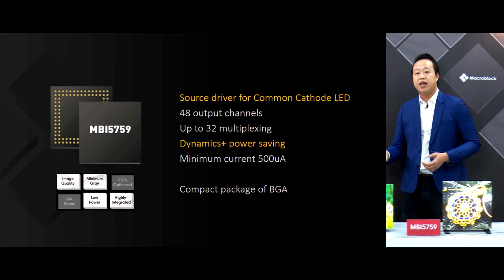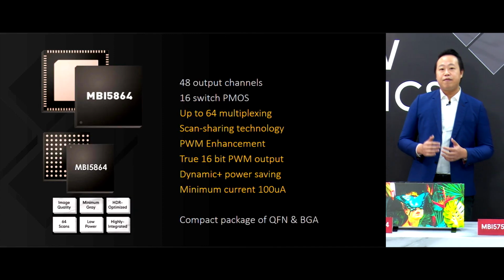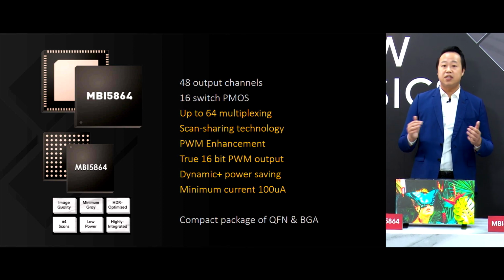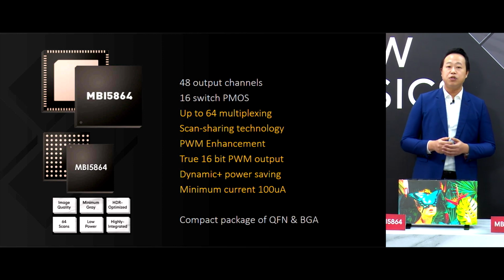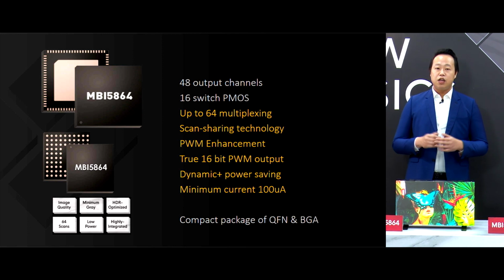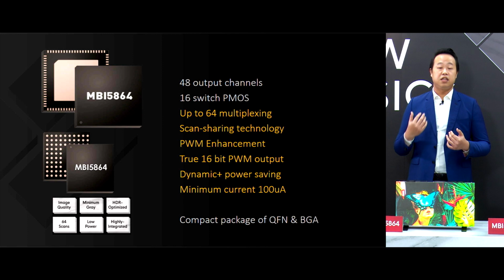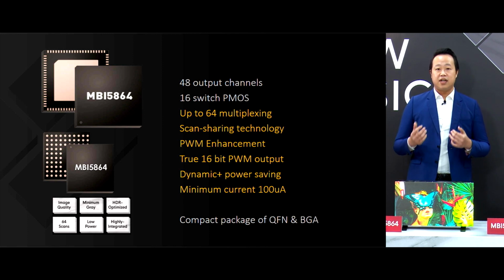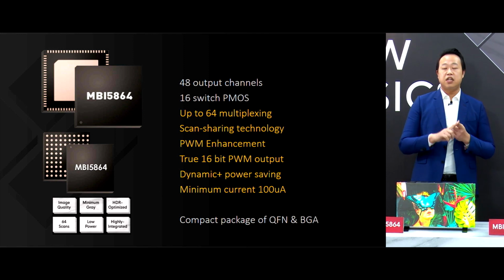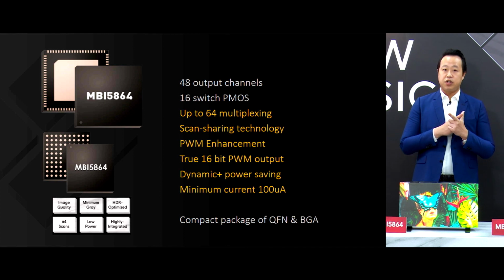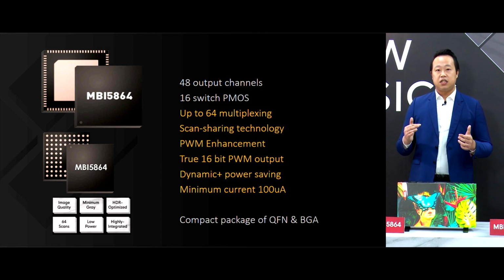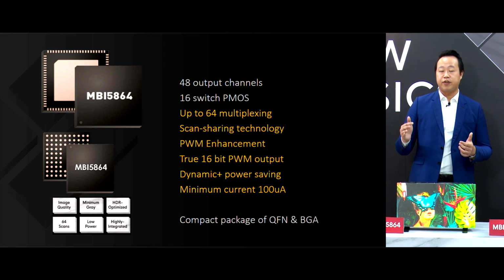And then we go to MBI 5864. MBI 5864 is our state-of-the-art driver IC, and it covers all the elements, 6 elements in new basics. I want to emphasize the element about HDR-Optimized. HDR-Optimized is what MBI delivered 2 years ago, and that is a driver performance related to display performance: 16-bit grayscale, and also 3840 Hertz refresh rate.